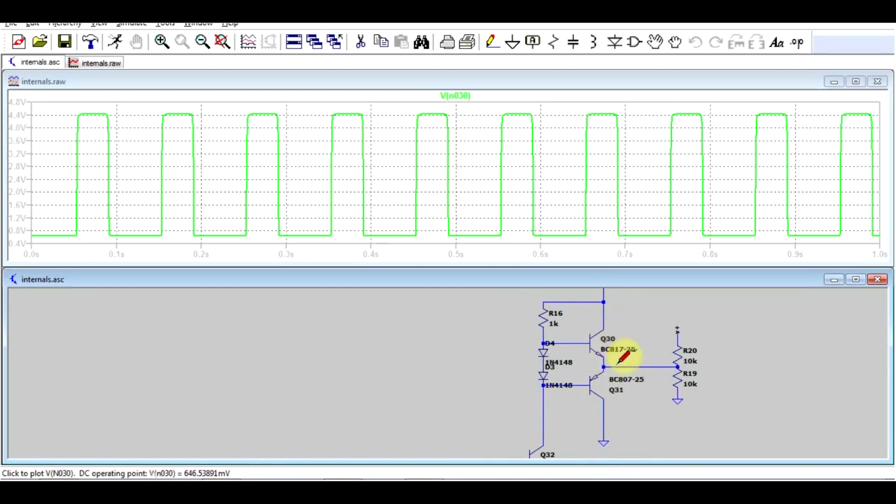If we want to drive the high side transistor, we need to be able to have a voltage in the base higher than the voltage on the emitter by around 0.6 volts, so the PN junction. The maximum voltage that we can get in the base through this resistor is the supply voltage, so 5 volts in our case. So no matter what load we put on the output, as long as it's a defined load, the base voltage can go as high as the supply voltage, but the emitter will always stay 0.6 volts lower than that, therefore giving rise to this 4.4 volt maximum limit if we supply it with 5 volts.